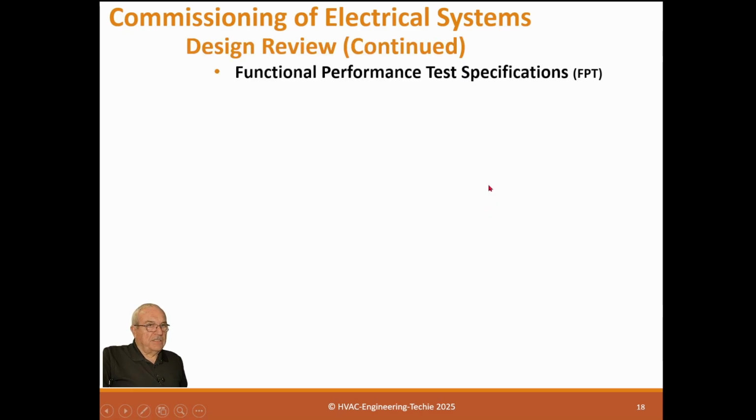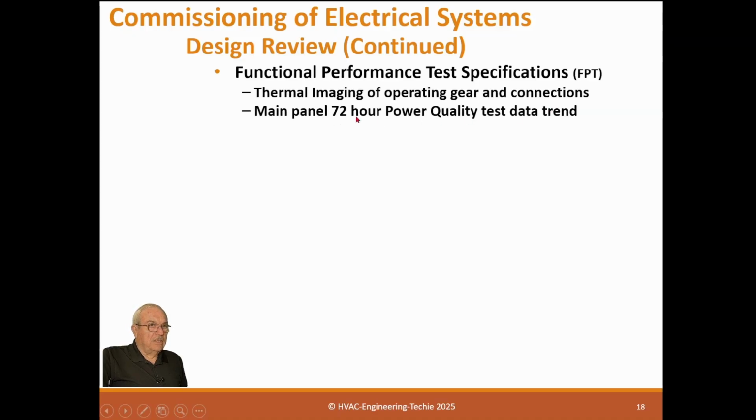Functional performance tests. Now this is all in the design review, right? So functional performance tests, how are they specified? And they're thermal imaging of operating gear and connections. This is a little bit more intrusive than you think because you have to put the system under load. So you have to bring in load banks to make sure the circuits are at design load and then you thermal test them. No good thermal testing if it doesn't have any load. I guarantee it's going to be fine. It only happens when it's under load.